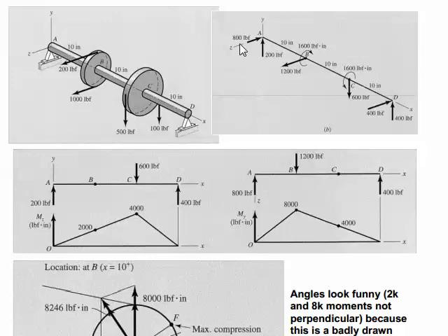In the other direction, we're going to have an 800-pound shearing load to get us started, and then the 1,200-pound at point B. This load does not come into this picture, but this 400 reaction does come into the picture here. And from this, we can also draw a moment diagram. We didn't draw a shear diagram, but shear would be a constant 800 in this region, minus 400 in this region, etc. I think you can picture the shear diagrams.